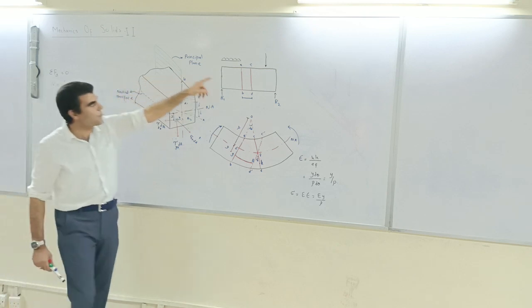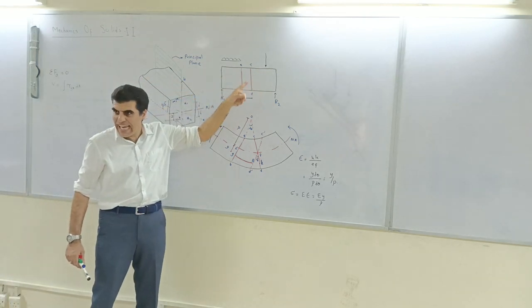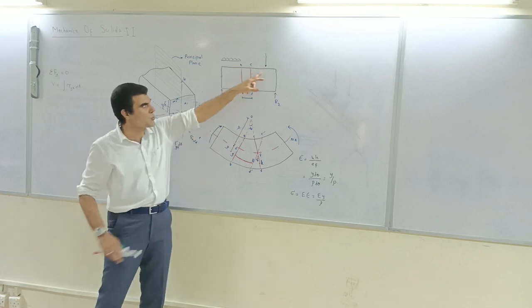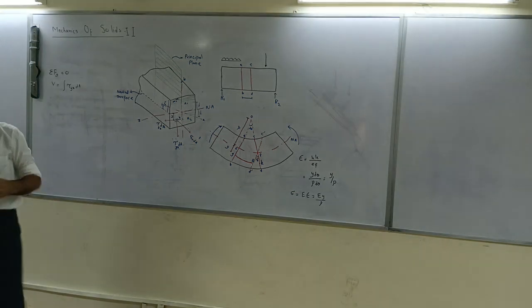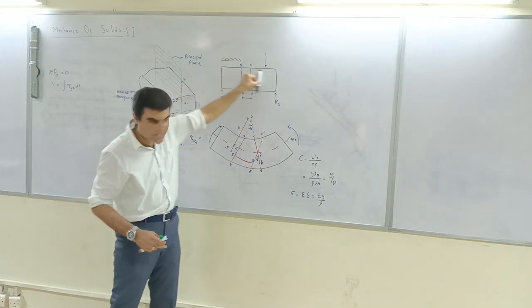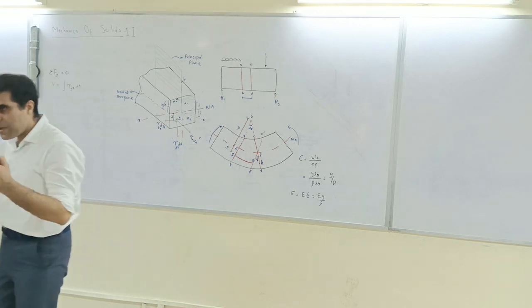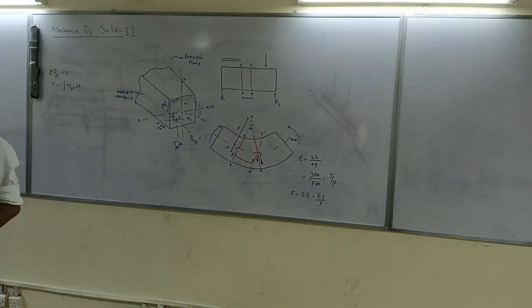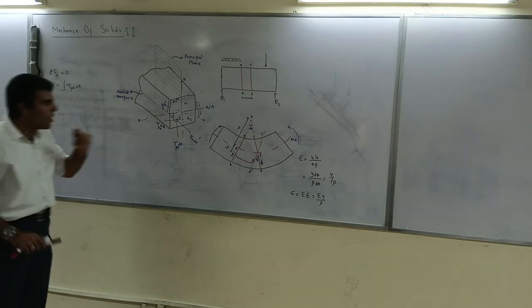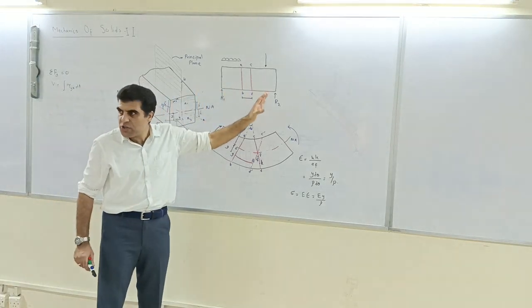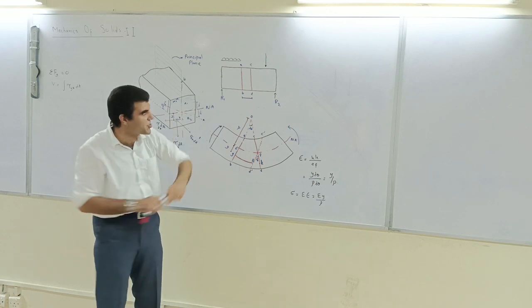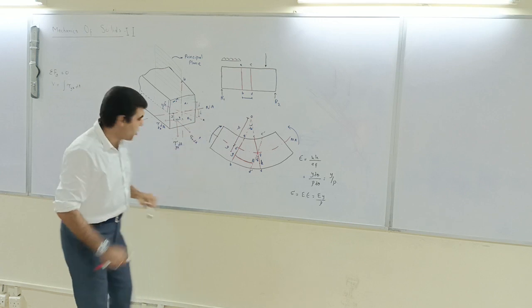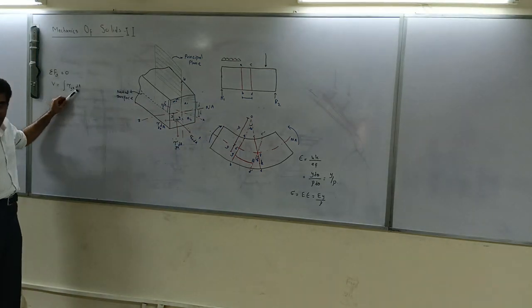Whatever force you apply on the cross section, that force will induce some shear stresses in the structure. That shear stress obviously varies along the length. That's why we draw the shear force diagram. The shear force diagram is for shear along the longitudinal axis. But this shear force also varies along the cross section. And tau yx dA, that is the equation for the cross section.